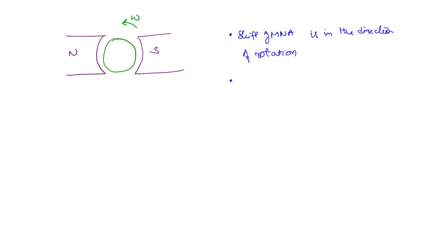And one more point is, when the rotor is moving in this direction, if you consider the south pole, then it is going to encounter this pole first, and then it is going to leave this pole, okay? So this is called the leading tip and this is called the trailing tip. Similarly for the north pole, this is the leading tip and this is the trailing tip. So you can write down, this is the leading pole tip, this is the nomenclature, just to differentiate. This is the trailing pole tip.